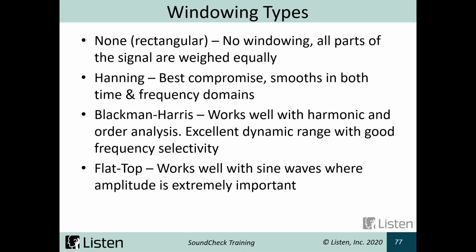If I, instead of 1000 hertz, read 1000.6 hertz, I don't really care, but I very much care that the amplitude is exactly accurate. If instead we use Blackman-Harris and the frequency wasn't centered, then it might instead say 1000 instead of 1000.6, but it might sacrifice amplitude. So flat top is very, very good in the amplitude domain, but it might not be as accurate in the frequency domain.